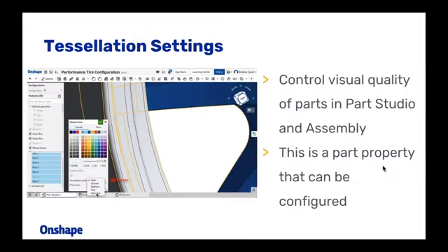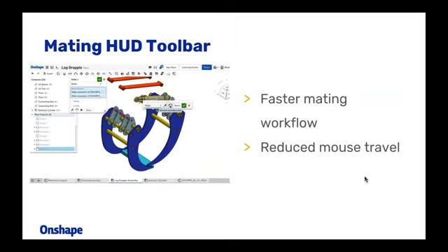Beyond that, we'll definitely be showing off some of the tessellation settings, which I found to be very useful within Onshape. I'm going to show you a cool workflow to actually configure the ability to have a high resolution model and a low resolution model, whether you're trying to grab a screenshot along the way or just work very quickly and not have any performance hits.